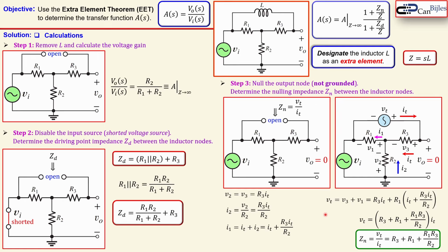Okay, this part is of course the hardest part because you need to apply the test voltage and the test current and then take the ratio, but the procedure is actually quite straightforward if you apply this several times and also use the handy work from the Kirchhoff's current law and the voltage law and the Ohm's law.